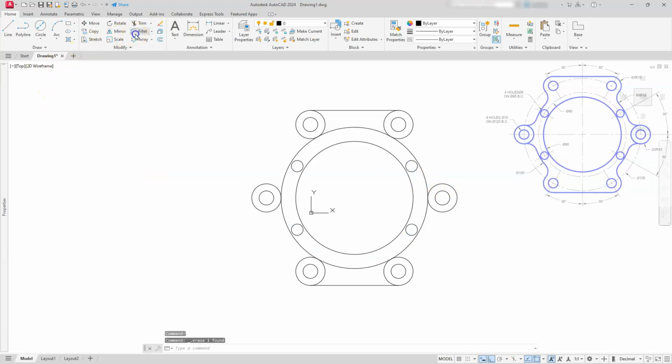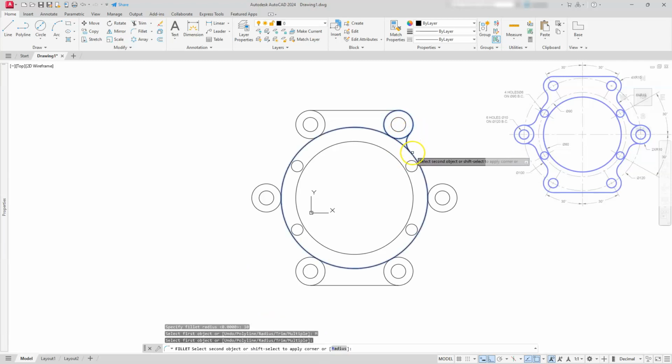Let's go ahead and use the fillet command. I'm going to go to radius. I'm going to set this radius equal to 10. And then I'm going to select the word multiple. When I do that, what I'm going to do is select the fillets between here. And I'm just going to kind of continue that around my shape. If you're looking at the drawing, it shows that I have 8 of these, so I created 4 of them so far. And then there'll be another 4 on the other side. So just kind of keep clicking these around until we're done with it, right?